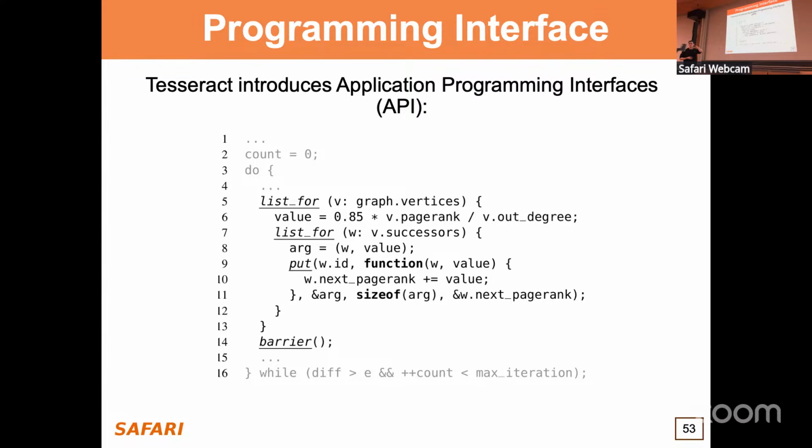So for normal memory, you have some kind of vendor-specific defenses against RowHammer, like target row refresh. Is there anything similar in HBM? I have searched for that. I have hardly found anything except for this paper that Harsh just mentioned, but I haven't looked too much into that.